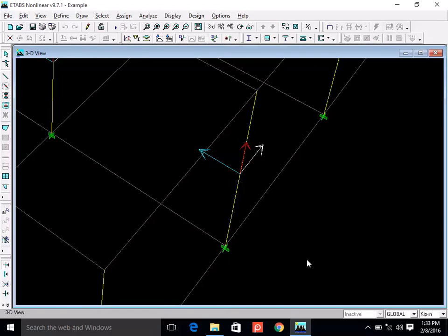Do you have bending moment in the beams like this? Very, very small magnitude, maybe in case you have horizontal load somewhere. This bending moment is about which axis? It's about axis 2. So that's why I'm saying that moment about axis 2 is insignificant in case of beams. That may be significant if you have horizontal loads, which may be present but not of significant magnitude. It may be due to earthquake, it may be due to wind forces, because both of them are horizontal forces.